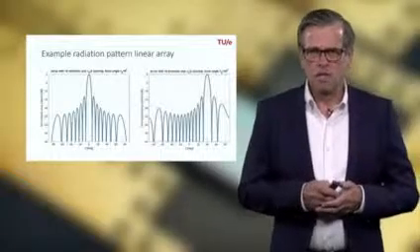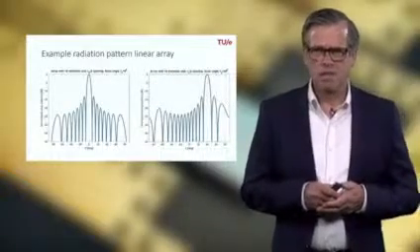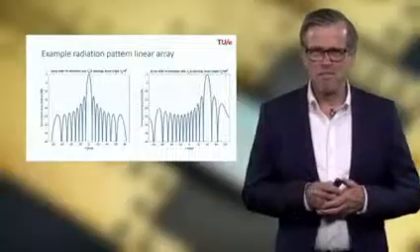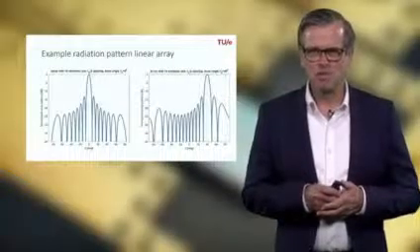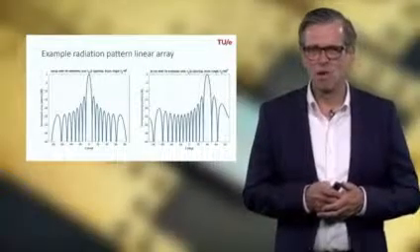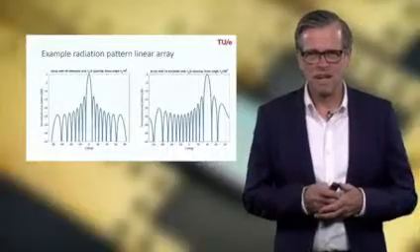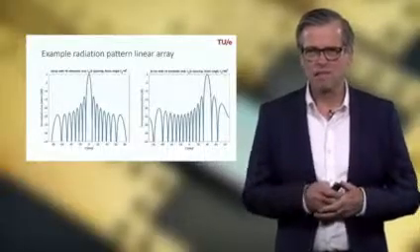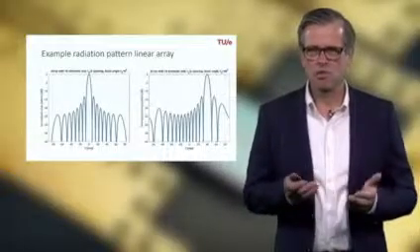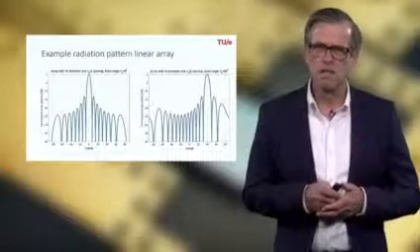Now, for the 40 degree scan case, you indeed observe that the main beam has moved to 40 degrees, and the side lobe levels have the same kind of peak level as shown for the broadside scan, so also at minus 13.2 dB.